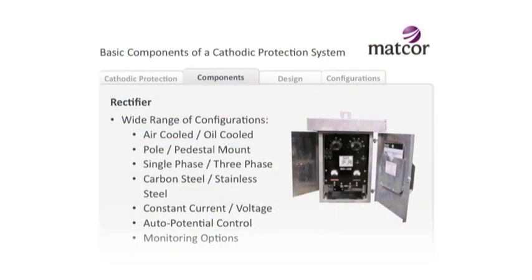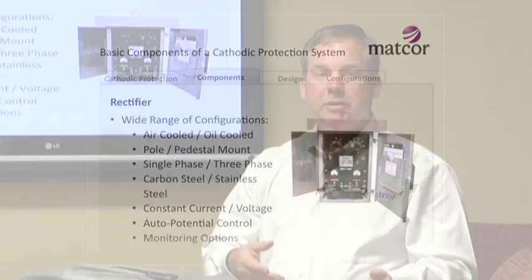A lot of these gas pipelines, they've got gas flowing through them anyway, or if you're at a wellhead site that doesn't have power, they've got a gas wellhead, but there's no AC power to it. Well, they're producing gas. They have natural gas. You could put a little generator there that burns the natural gas, creates electricity to run your CP system. Solar power with batteries. You get a solar power panel or several solar power panels tied to a battery system. The battery is DC power. You hook that up to your CP system. You're off and running with no electrical power.